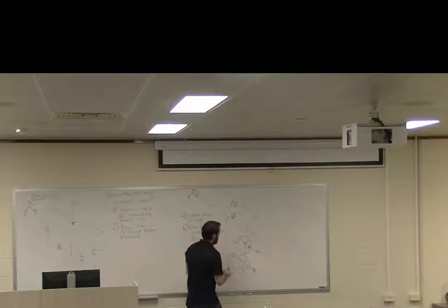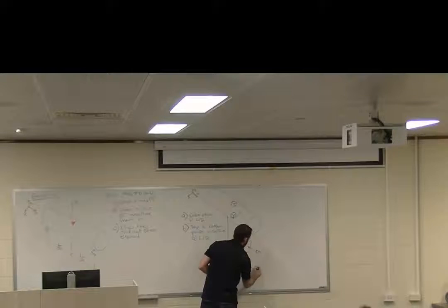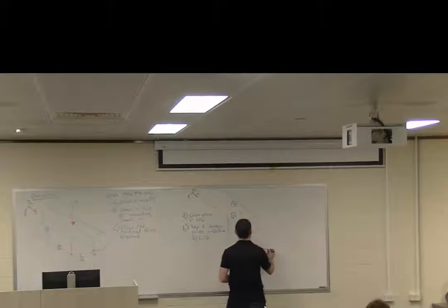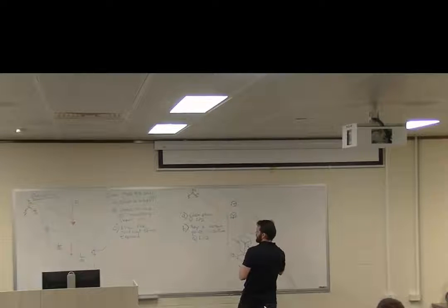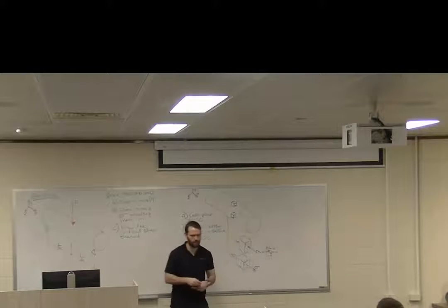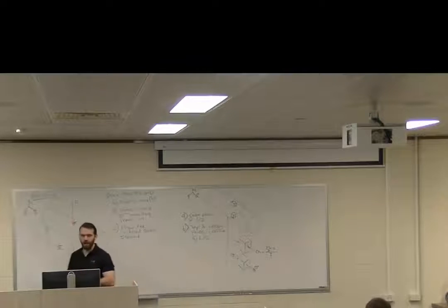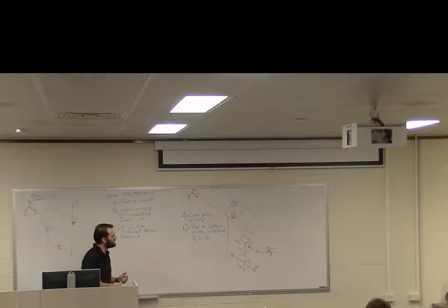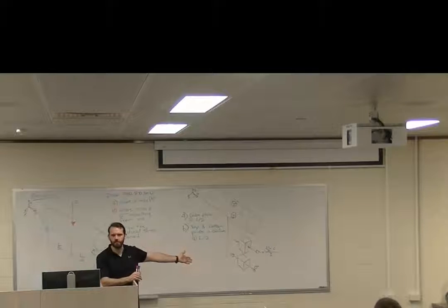Okay. So compression stress, tension stress, and that equals, let's say, what do we calculate? FL on 4 times whatever C is on I. You can say something like that, or you can just say sigma. Obviously, we'll have values when we're actually calculating these things. All right, so is everyone comfortable doing that? Or mostly comfortable doing it?